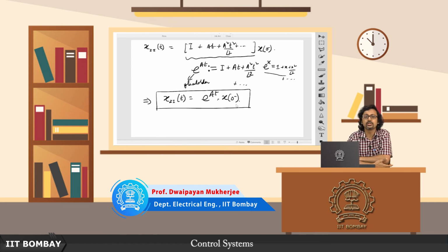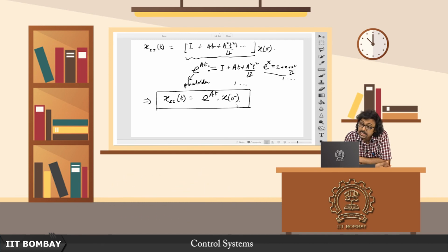So in the next lecture we shall take up some examples and we shall see how you can get the Laplace inverse of this sI minus A inverse. Already we have seen some of those transfer functions, how they look. Now if you want to evaluate that, it will be pretty laborious. Even for a 3 by 3 system you have to carry out 9 inverse Laplace transforms, pretty laborious.